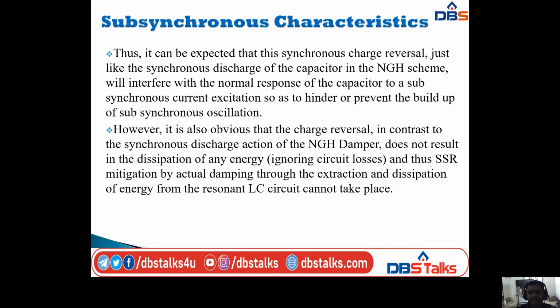Thus it can be expected that this synchronous charge reversal, just like synchronous discharge of the capacitor in the NGH scheme, will interfere with the normal response of the capacitor to a subsynchronous current excitation so as to hinder or prevent the buildup of subsynchronous oscillation.